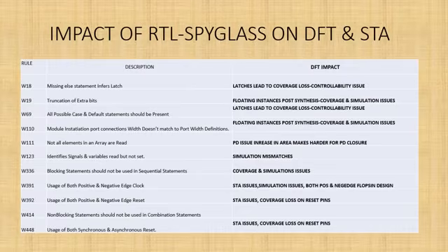To avoid such issues, we need to place negative edge flip-flops at the initial level and then the positive edge flip-flops followed by them. Usage of both positive and negative edge resets may also lead to coverage loss on the reset pins and also STA issues. Again, the usage of both synchronous and asynchronous resets will also lead to coverage loss on the reset pins.